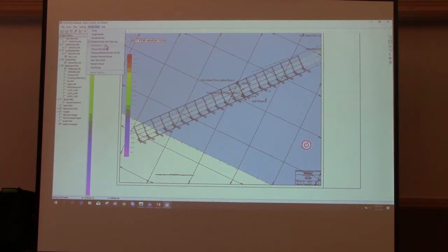IHO border is grayed out at the moment because that will only work at preset 90 degrees, 180, 270 degrees, and 0 degrees, just the way it's designed. So I have my plotting sheet rotated for this survey, so I can't load up the IHO border.